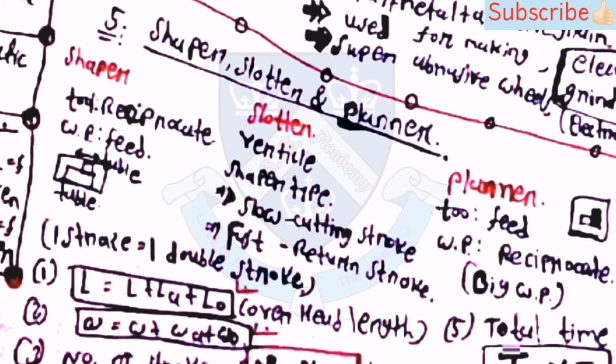Then after that, shaper, slotter and planer. In the shaper, the tool will reciprocate and feed is given to the workpiece. Then in the slotter, the stroke is vertical. The cutting stroke is slow and the return stroke is faster. Then in the planer, the feed is given to the tool and the workpiece will reciprocate.